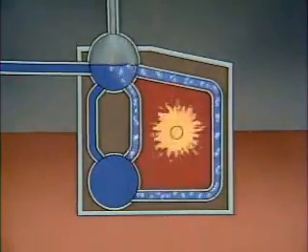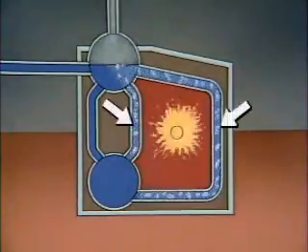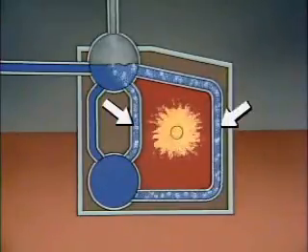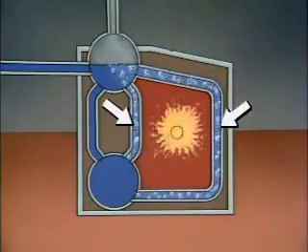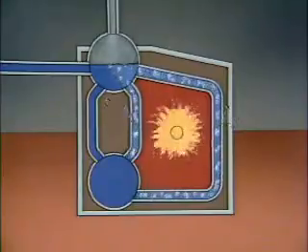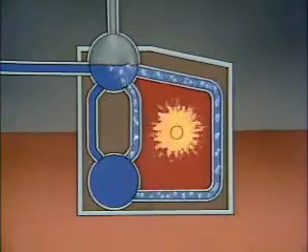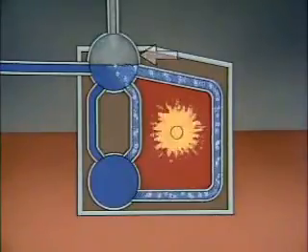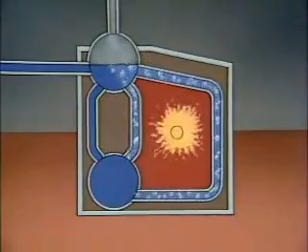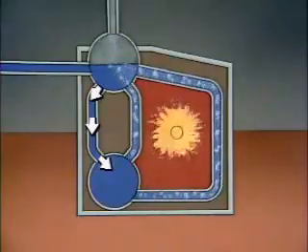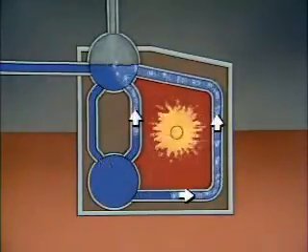As combustion occurs, the water tubes that surround the combustion area heat up. As heat is transferred to the water in these tubes, the water becomes less dense and lighter than the cooler water elsewhere in the boiler. Some of this water turns to steam. As a result, the heavier, cooler water flows downward into the lower drum, and the lighter steam-water mixture flows into the steam drum.